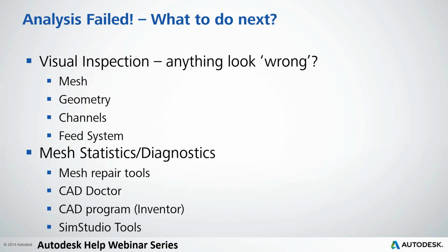So sometimes you might have to go back and remove unused properties within your model, or even in some cases export as a patran file and then re-import it into Moldflow, because then you'll be able to reset the properties behind it. What that'll do is clear out and reset the solvers behind it to be able to read those properties.